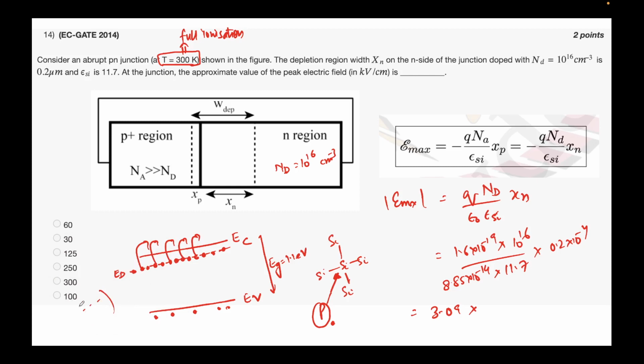So if the energy gap is smaller, then a lot of electrons can be excited at room temperature, but some energy has to be there. That's why, even at room temperature, we'll assume that all the dopants have been ionized. This means they can contribute to the electrons.